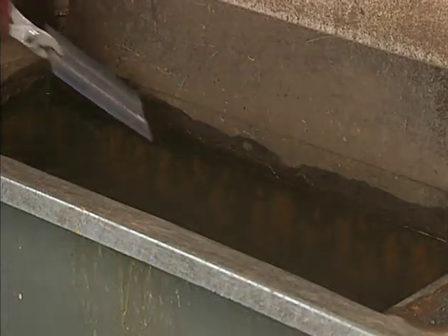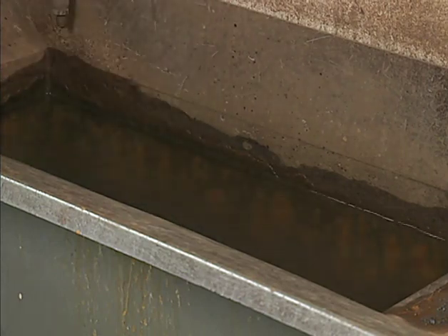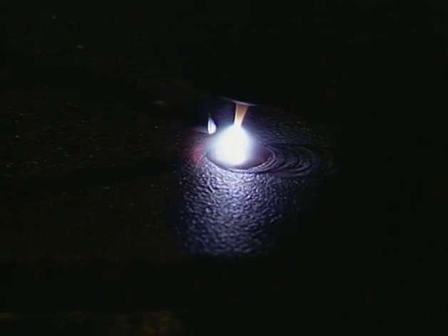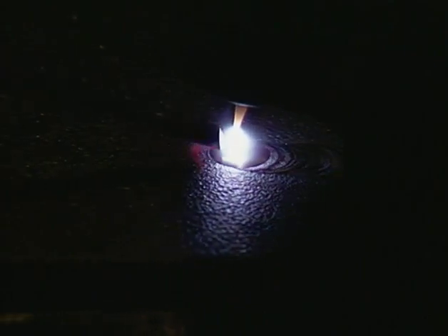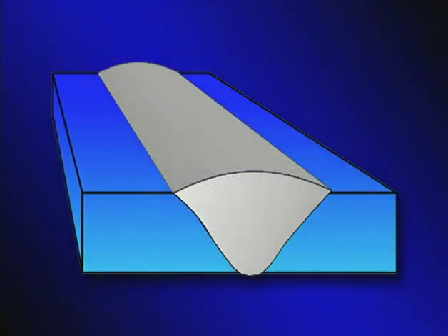Quenching occurs when you dip steel into a quenching medium like water or brine immediately after welding it. Quenching also happens when the heat of welding is conducted away too quickly by the surrounding base metal, especially on thick sections, and when martensite forms in the weld or in the area around the weld called the heat-affected zone, it can result in cracking.